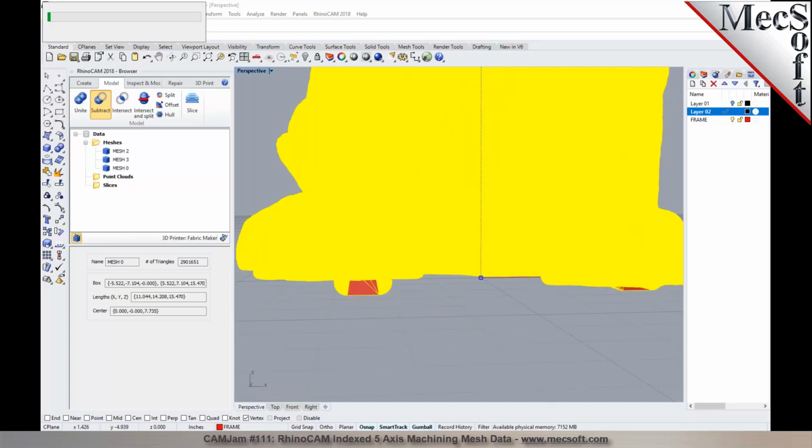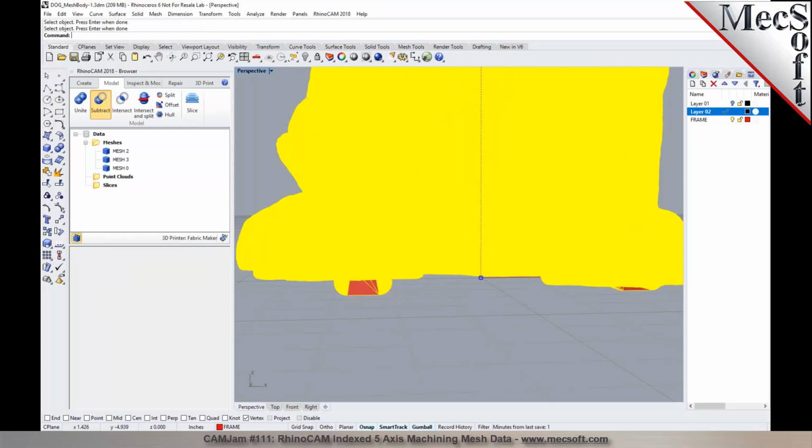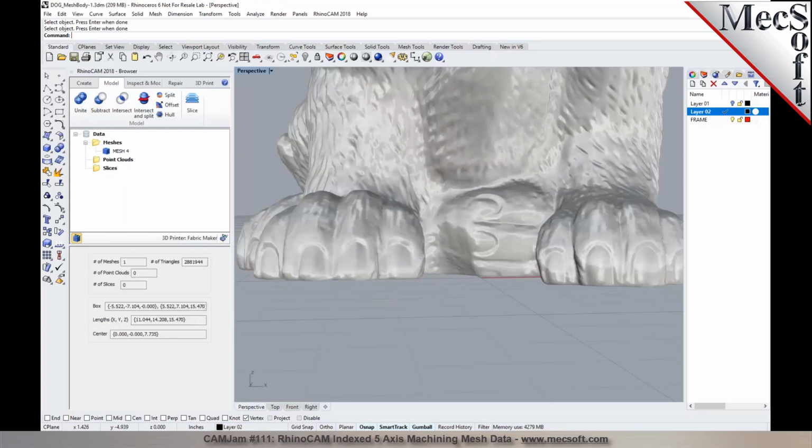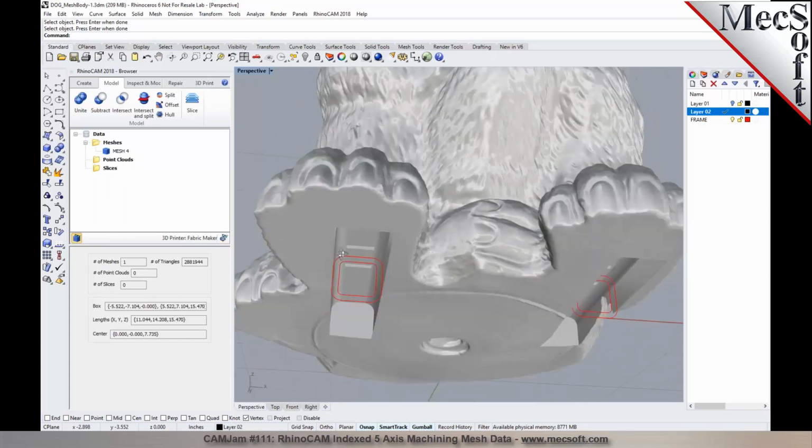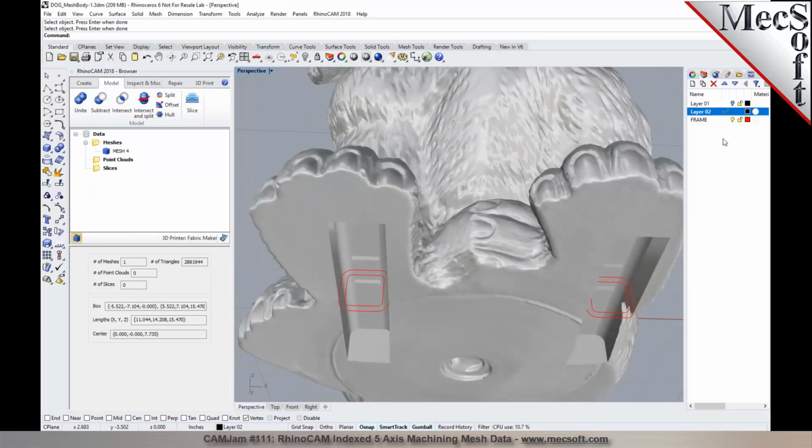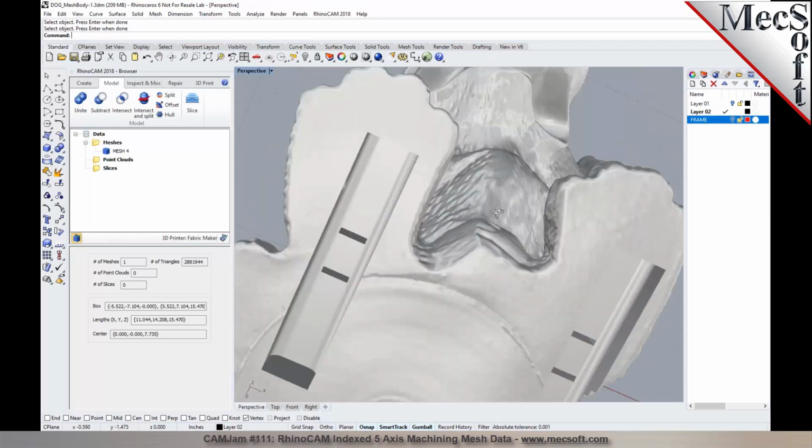Yeah. Do you have any examples that we could look at? Or I can see what we have here and do a mesh to NURBs and see how that works. We can. One of the nice things with our CAM milling solution or machining solution is you can directly machine meshes all the way up to index 5-axis, and for simultaneous 5-axis, we can use meshes as gouge check surfaces, and we can have to model a drive surface.